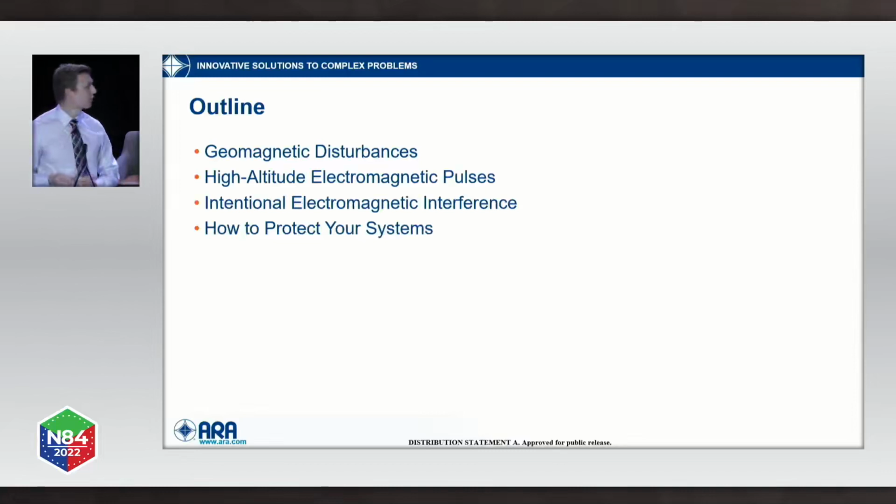So before I actually jump into this, I want to talk about the mechanism by which electromagnetic energy is actually going to damage electronics. Much like an antenna works, it's a conductor that's meant to pick up electromagnetic energy, right? But when electric fields are so large, they can actually drive currents in places that currents are not supposed to be going. And if you get a large enough current in a small enough area, you can get heating, you can burn out devices. Sometimes just driving current where it's not supposed to go can flip transistors and turn parts of your circuitry on that should not be on anymore. And it's these kinds of variations that lead to damage in your equipment.